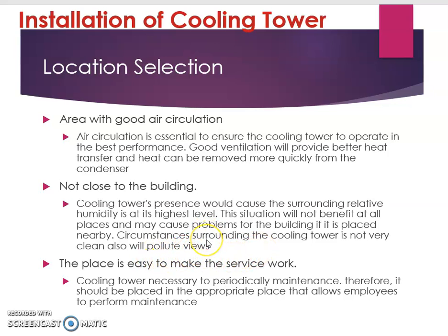Because usually cooling towers have very high humidity, fungi will easily grow in a very humid and wet location. So it is important to make sure the rejection of heat and the fan is not near the building.